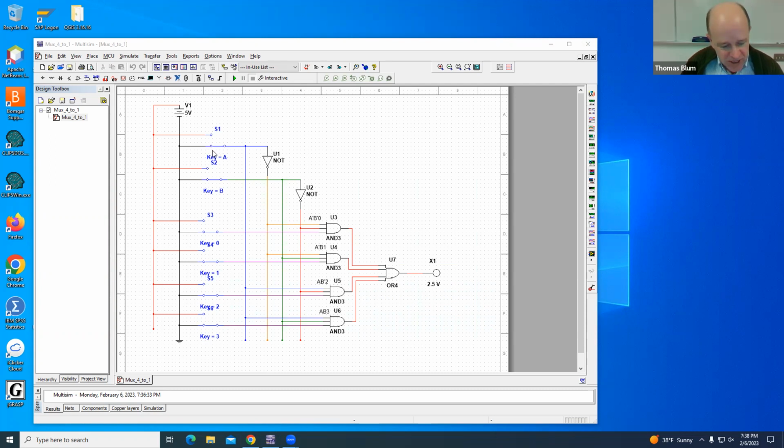So here in switch A, if I'm in the workspace and I hit an A, the switch goes up and it's connected to this red wire, which is connected to the top of the battery, and therefore 5 volts is a high. If I type A again, then I'm connected to this black wire, which is connected to the low part of the battery and to the ground, so that is 0 volts. So I'm putting either high or low into A, and that is true for all these inputs.